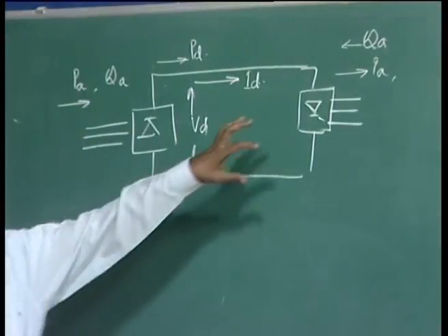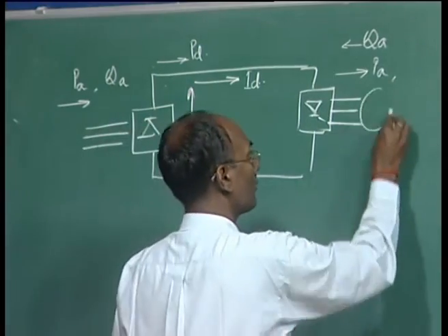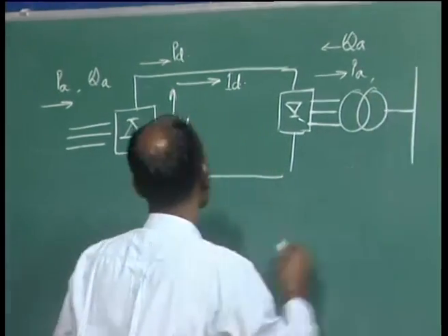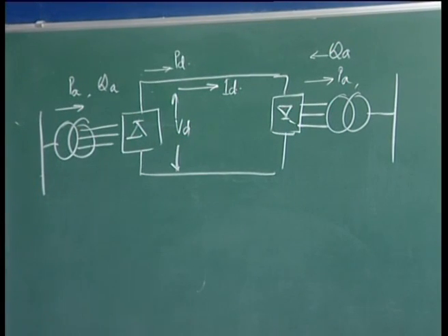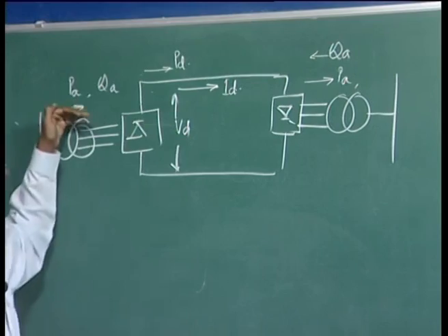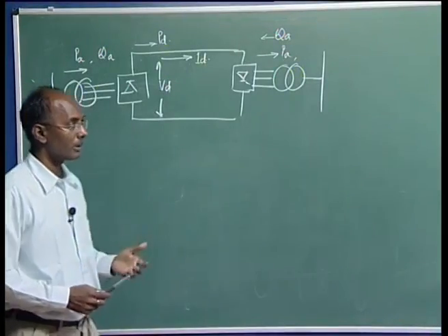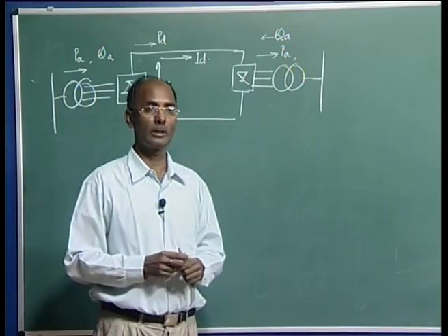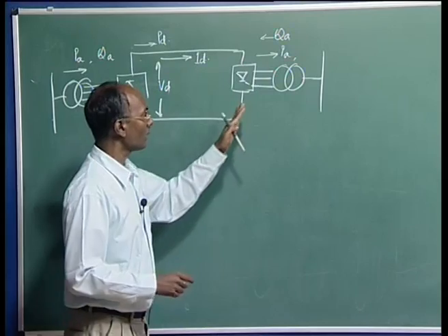Means it still consumes reactive power from the AC system. This side we are talking about the transformer, this is the AC bus. So the reactive power is basically required at both ends, and I have already discussed the filters.